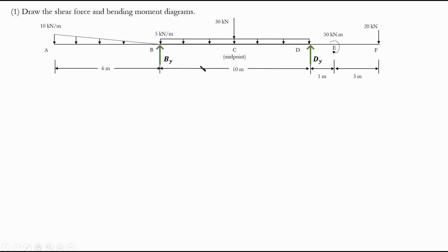In this case, we're neglecting axial load because there's no axial load that we can see. This structure is determinate, and we're not dealing with a frame type of situation, so axial load here is neglected. Also, the stiffness throughout the beam is the same. Now we can find the reactions by taking the moment about either of these points, point B or point D. Why? Because if we take the moment about point B, this reaction force goes through this point. What does it mean? It means that the moment this force creates about this point is 0, right? The lever arm is 0.